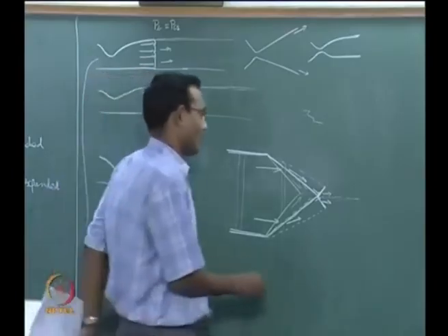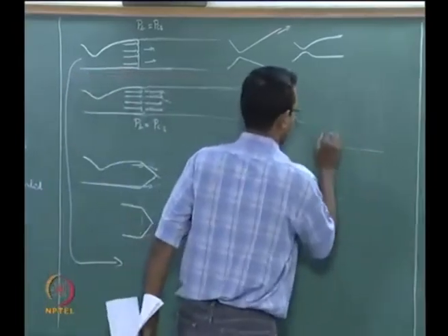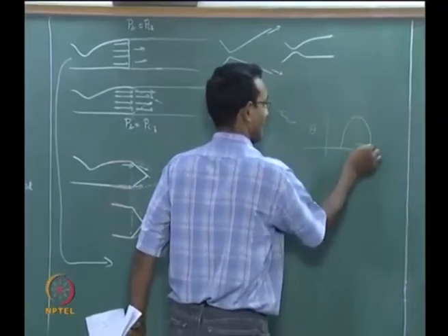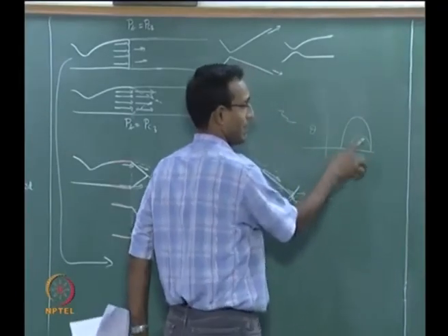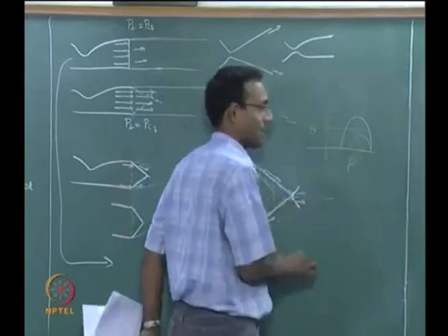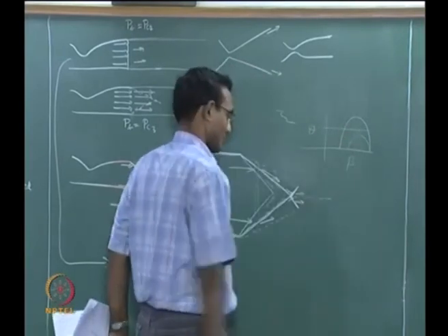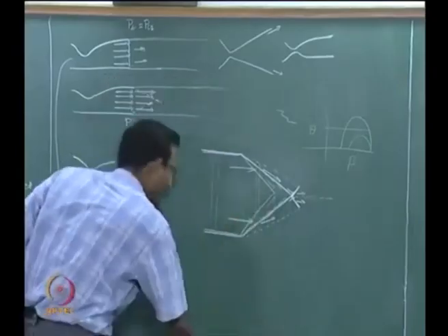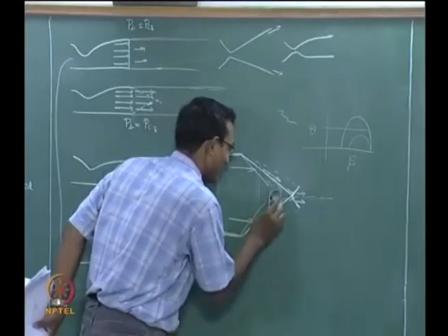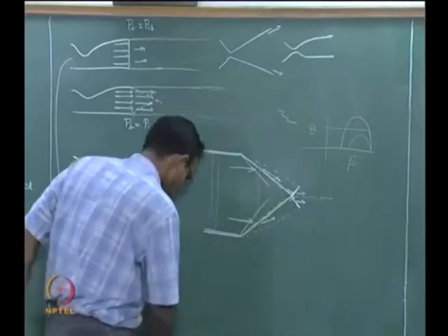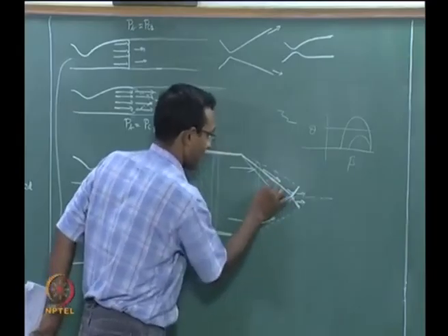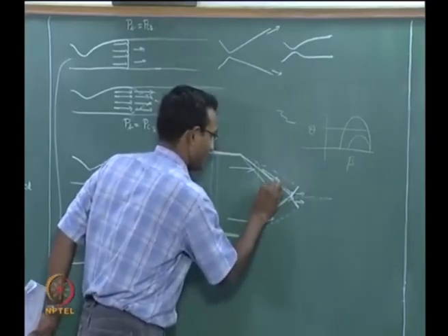What happens at that point? We will cross that theta beta M curve. If it is a weaker Mach number and I want this strong thing to happen, it has crossed. So what happens in that situation? It becomes a Mach reflection. That is what I want you to think about now. Since I have introduced you to the other simple thing, now you can think about a Mach reflection. Along this dotted line, there is going to be this Mach reflection happening out there.